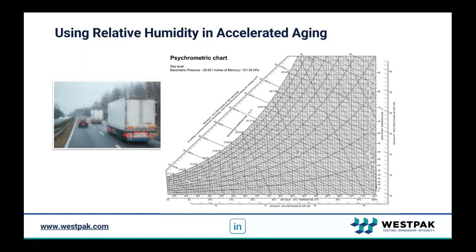So the standard recommends between 50 and 60 degrees C and between 45 and 50% relative humidity. So it's kind of in a conservative area. It doesn't do really high temperatures and really high humidities because that may adversely affect the way your product accelerated ages. And the way I kind of remember this is I think of brownies because I like food, and the